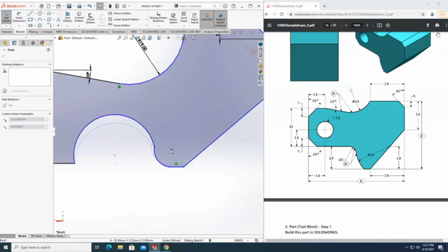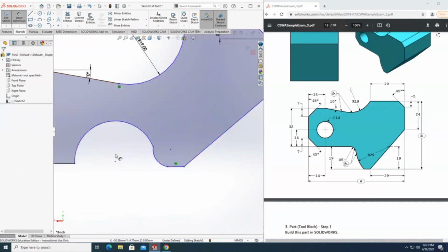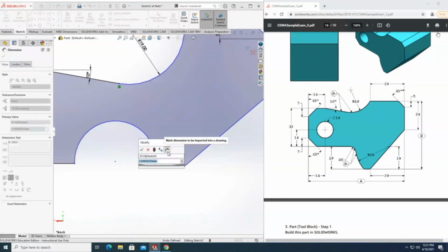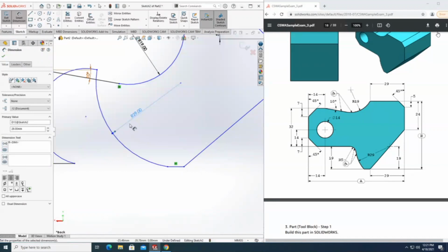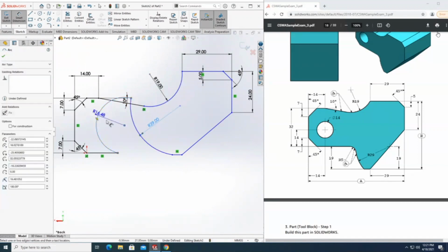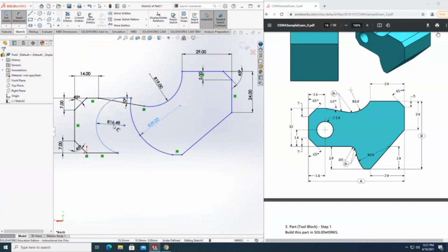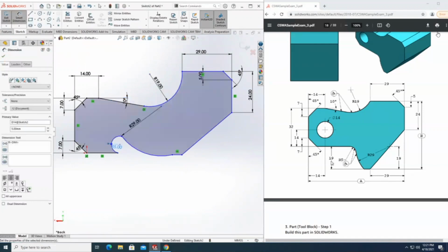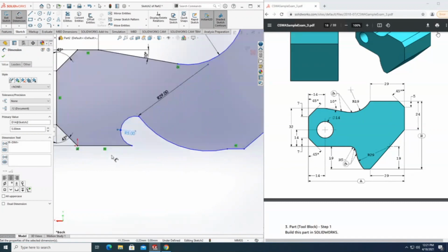If you look at it, you can kind of drag this out. And what you can do is, wait, let me first give this a bigger radius. Let me just give it 29 so that it can actually give the shape that we want. So if you see here, it kind of messes everything up. What we can do is fix it by making this arc a lot smaller. And this arc is going to be a radius of 5. So that's what we're going to do. And it gives a general view again of the model, but we can see that there's a sharp point here. However, when we look over here, it looks tangent, and that's what we're going to try to fix.